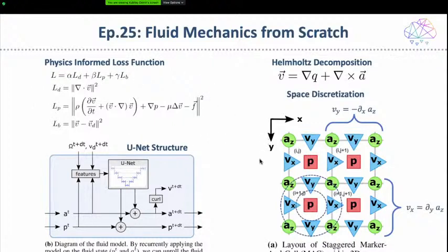And one thing that's also similar to the other machine learning approaches or numerical integration is that they actually use a discrete grid for representing the variables, and also specifically one that you might use in a fluid dynamics application. Because here all variables are not at the same place. That is very convenient for determining the discrete representation of the derivatives, because the difference that you are computing is always centered by the two values that determine the difference.